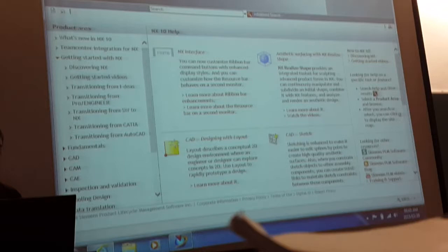Alright, so we've got this part, and we roughly know from the basics of finite element analysis that we're going to discretize this solid, right, with elements. Okay, and those elements are going to enable us to break the complex problem down into a whole set of small, simple problems. Okay, so we need to discretize this solid. Right. In addition, as we will learn in the coming lectures, we need to apply material properties to the solid, so we need to define what the material is associated with the solid. We need to select what meshing characteristics we want, what element type we want. We need to also apply boundary conditions, right?